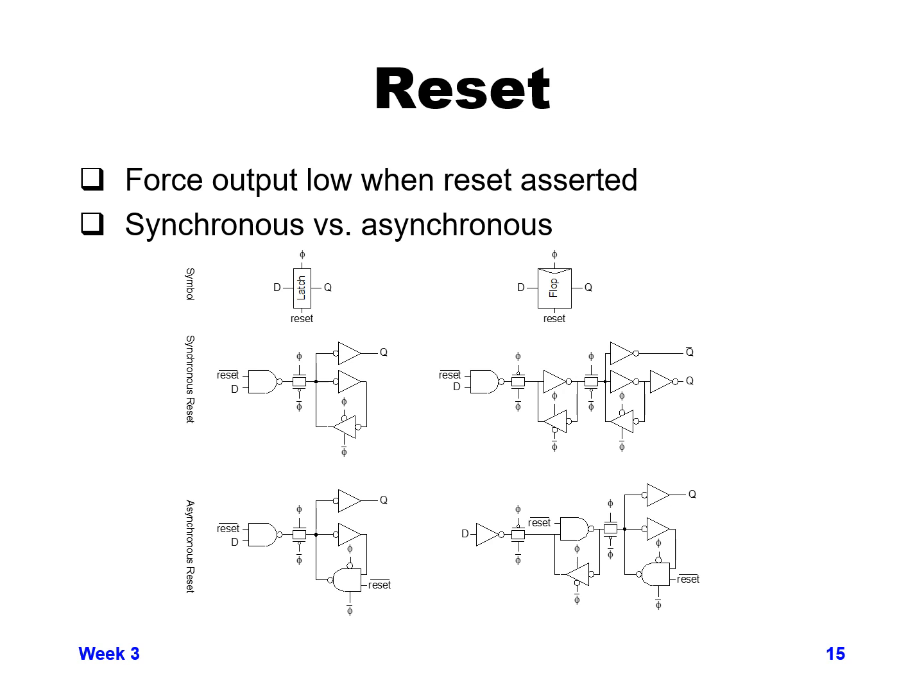So in this case, when the latch is open, the tri-state feedback is off, but we're sampling the value from the input, and you'll get the reset value going through. When the latch is closed, the tri-state feedback will be overridden by reset, and it will go through. So as soon as reset comes in, it will go through and overwrite the value of the latch, no matter what the clock value is.